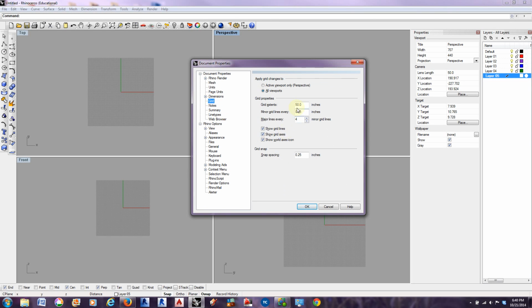Grids. So this grid is a 50-inch grid, and it's basically defining this 50 inches. So overall, it's 100 inches by 100 inches. And then the grid lines themselves are spaced every 0.25 of an inch. It's a little extreme, but your snapping to spaces, when your grid snap is on, is set to 0.25 of an inch. So that correlates with the grid lines as well.